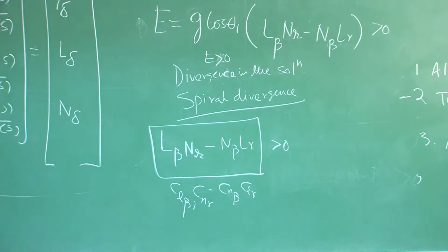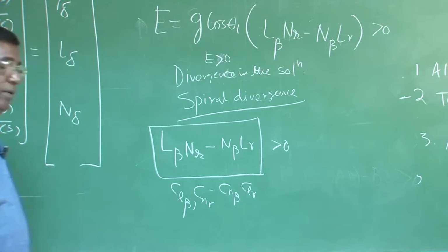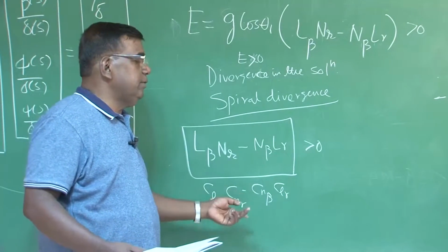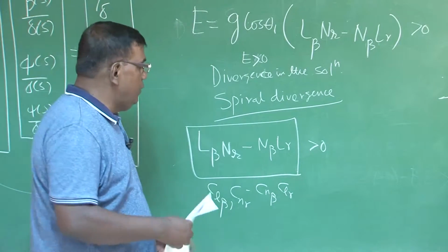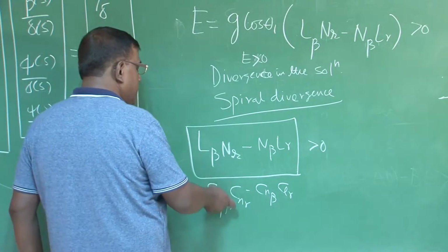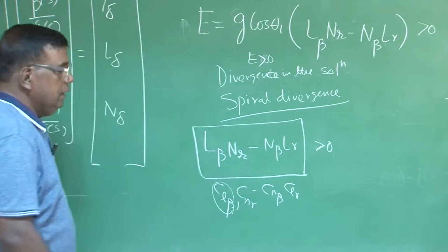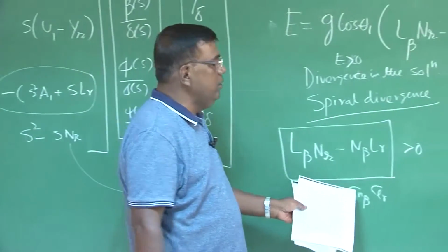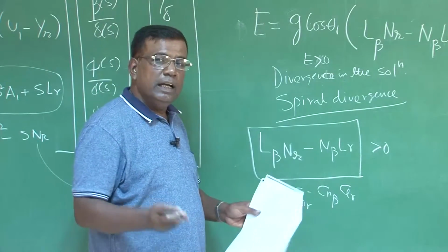So you could see these 4 derivatives are to be created in the airplane through layout of your tail, wing, etcetera, such that this is satisfied. Although we are talking about CL beta for lateral stability in static sense, you could see that it also plays an important role in dynamic stability. So that is the connection.